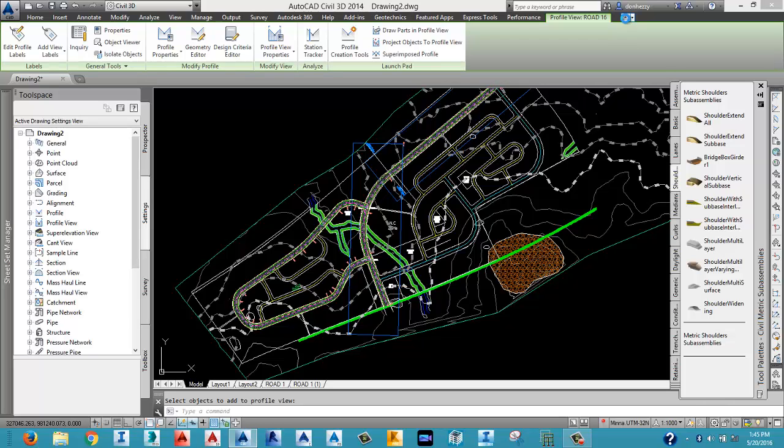So you go to your plan to select the first block this time. Select the first block. As you select it, you can even select the handle if you are finding it difficult to select from inside. Enter, space bar.